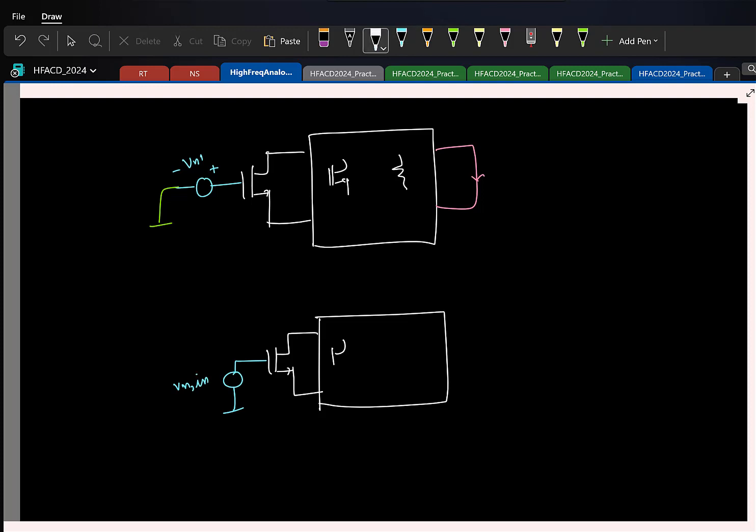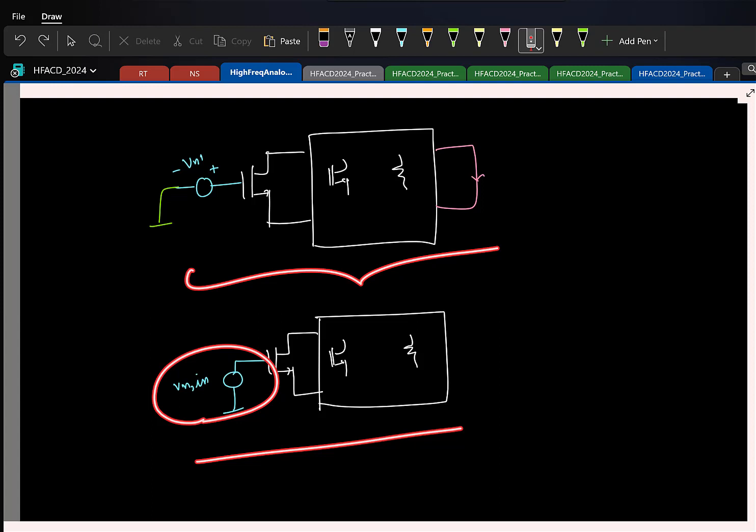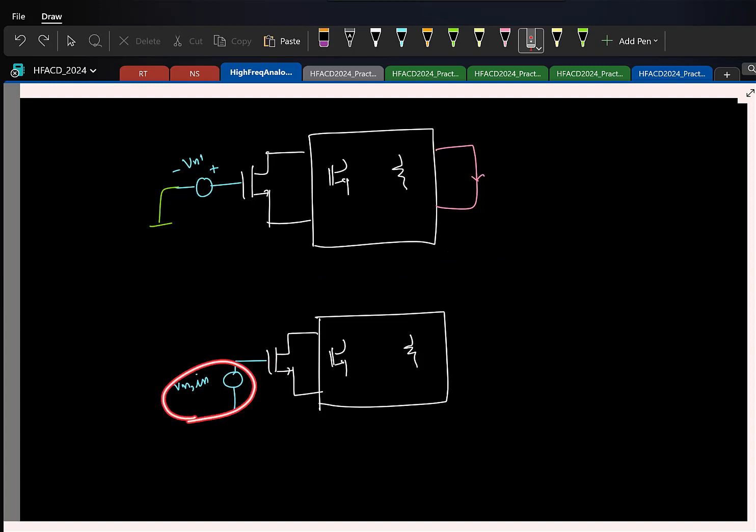So this is the same network without any noisy elements, I mean, without any noise in the network. That's fine. So this is our original noisy network. We are trying to model this using a single voltage source. Now this input referred noise voltage will have contribution from this transistor, and all the other noise sources inside, right? Now to model the noise generated by this input transistor, I can consider it to be an equivalent voltage source at the gate. So now can you tell me what will be the contribution of this transistor to this overall input referred noise?